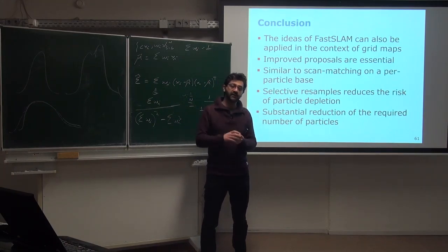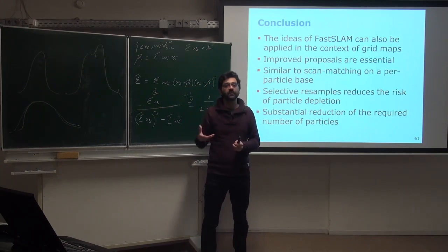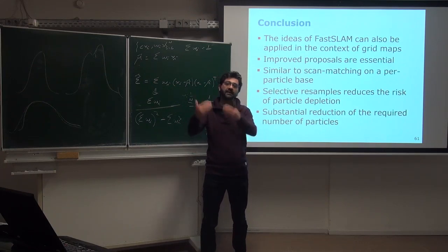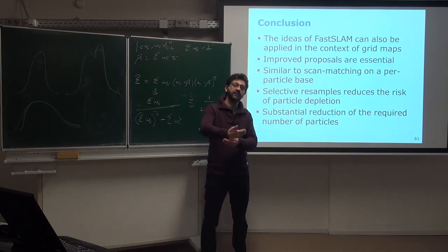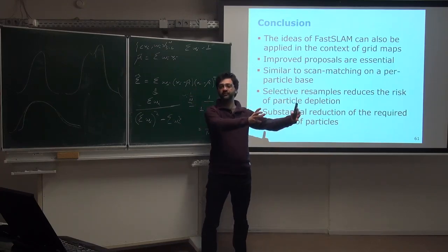One is that we take a Gaussian approximation of that centered at the scan matching optimum, where we take this optimum from the scan matching, we uniformly sample around that, and from this sample we compute a sample mean and sample covariance, and we use this mean and covariance to sample again new samples for the particle filter. So there are these two-step samplings where we take the odometry, scan matching, take the maximum, uniform samples, compute mean and covariance. This is now our proposal, and then we do the sampling of the proposal.